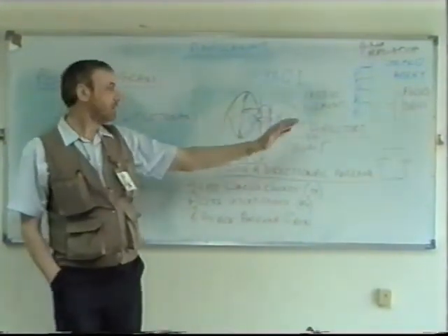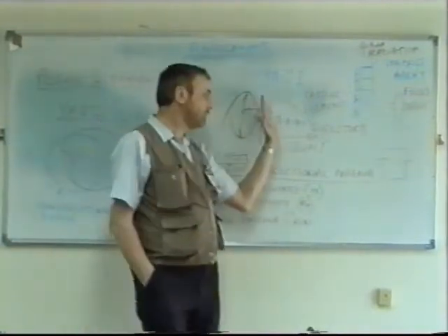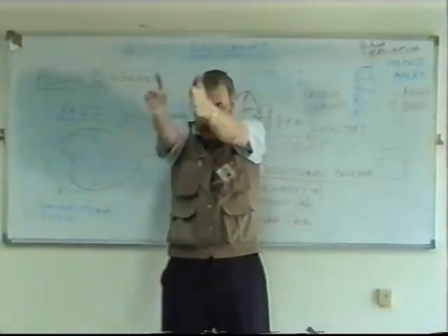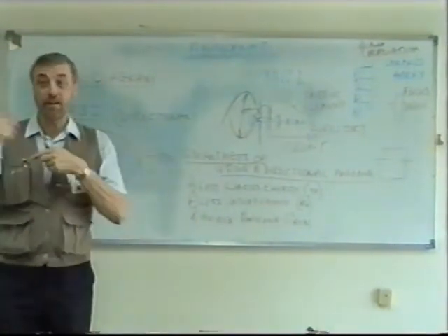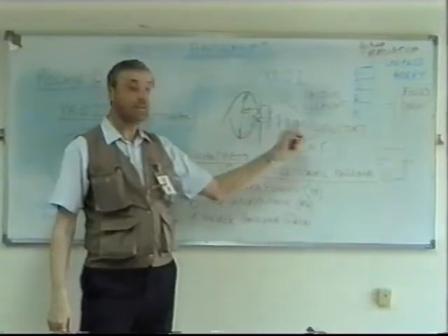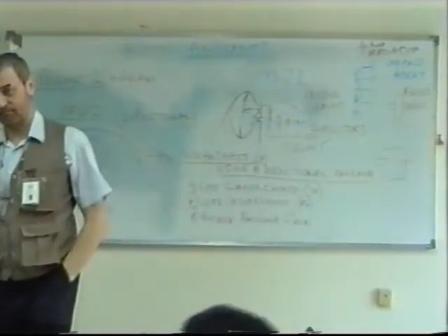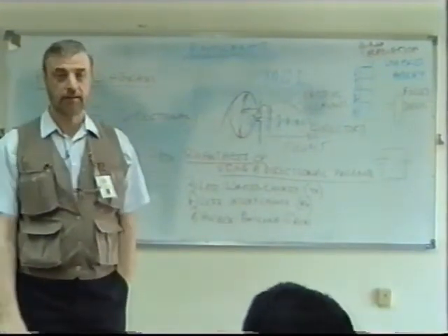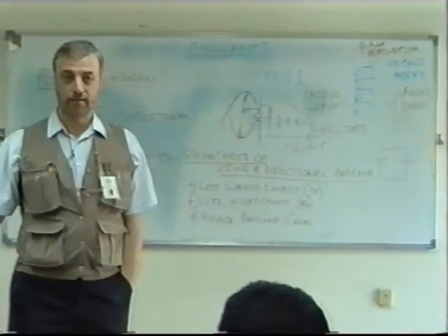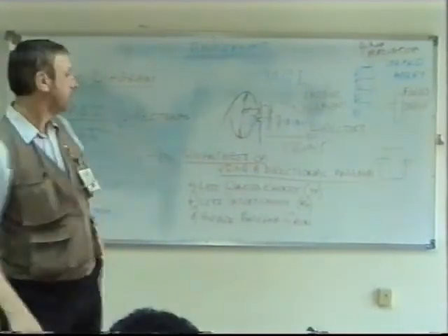Are you talking about the antennas that we use for the high...? I'm talking about the antennas that work in the Yagi antenna. In theory, yes, we can have hundreds of elements and make it very, very narrow and tight and directional. But in practice, you wouldn't do that because you waste a lot of energy in the elements. That's the problem. What about the distance? Range, it's line of sight. End of answer. Nothing to do with directional.